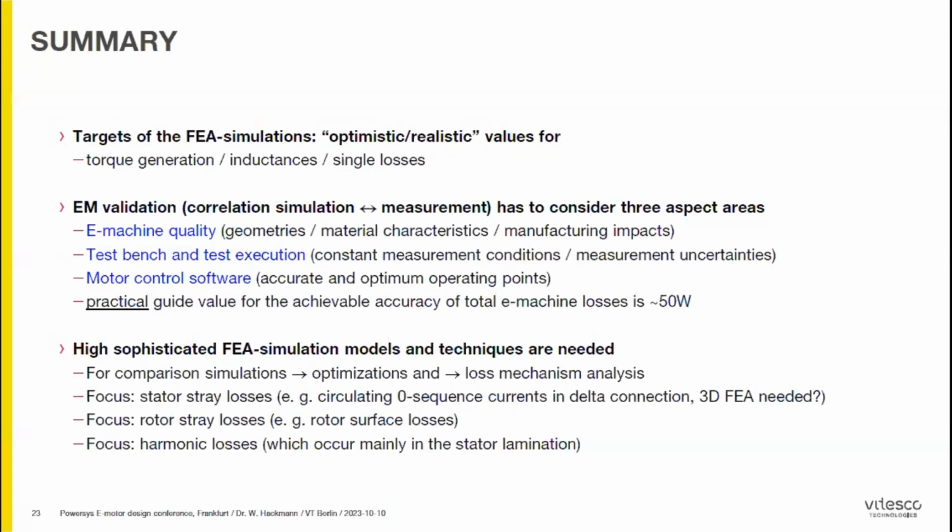From measurements, I can say harmonic losses are not ohmic losses, so this is safe. So we have ohmic harmonic losses, but these losses are very small. They are not mainly occurring in the stator lamination. So out of many measurements, we saw this, and this should be the starting point for the analysis and for the application of certain simulation strategies.